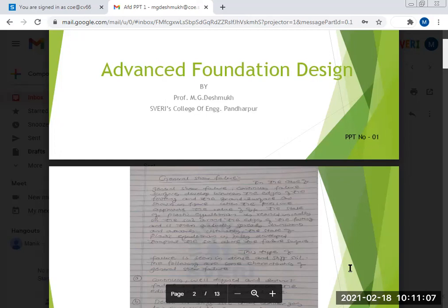Second thing is general shear failure में जो रहता load settlement curve. This is very important. What is the load you are applying and what is the settlement? That is very very important calculation. आप इतने लोड पे कितना सेटलमेंट हो रहा है. You will draw a graph here. Whenever you study in detail about these failures, you will draw a graph. Okay, on the axes you take loads and you take settlements.